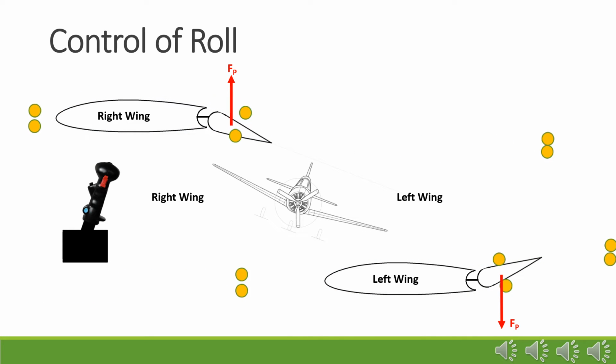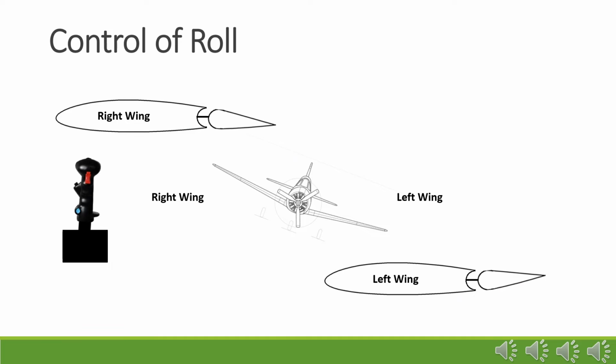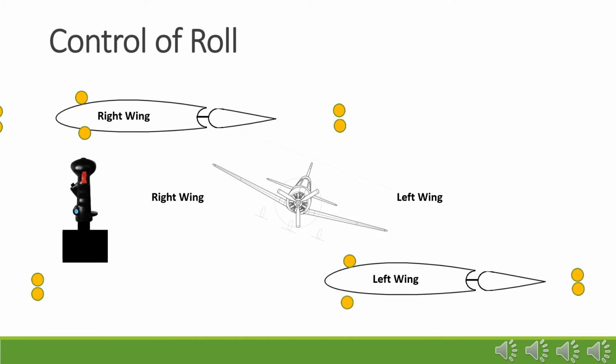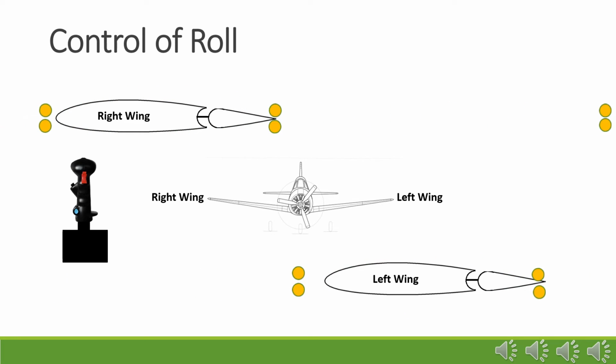By returning the control column to the neutral position, the ailerons once again return to the center position. The normal and perpendicular forces are eliminated, while the drag force is minimized. The aircraft would stop its roll motion and continue on a straight pathway. This will not, however, return the aircraft to a level attitude unless it was either currently in level flight or rolled back to level flight.